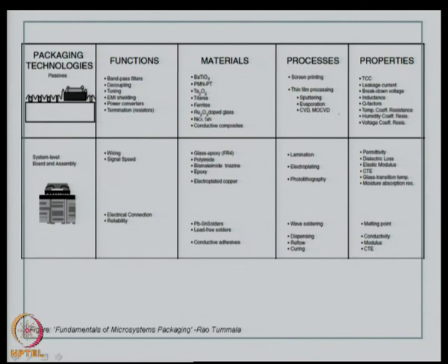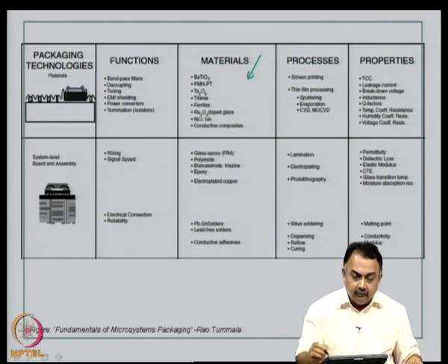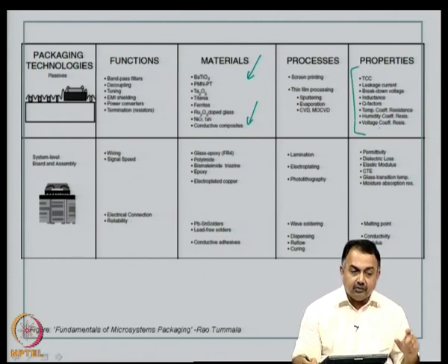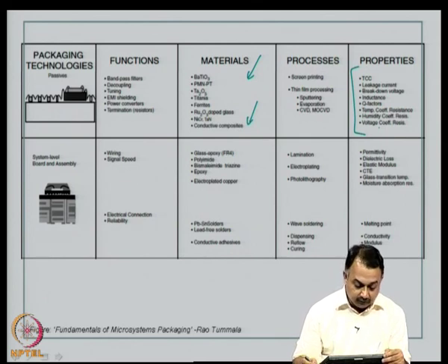As far as the passives are concerned, there are various materials. Just now we have seen thick film hybrid circuits or thick film LTCC processes, materials like barium titanate, tantalum oxides, ferrites, ruthenium oxides, polymer thick films, carbon paste, conductive composites, etc. All of these are new materials that are being used, and we have just now seen various properties that are key to passives technology like TCC, leakage current, Q factor, temperature coefficient of resistance and so on.